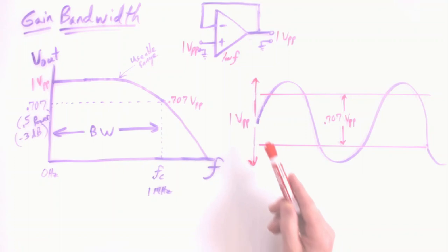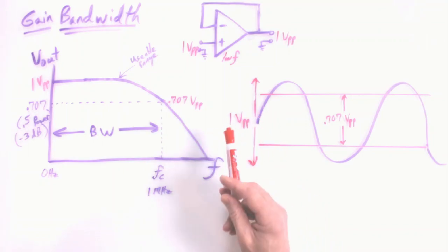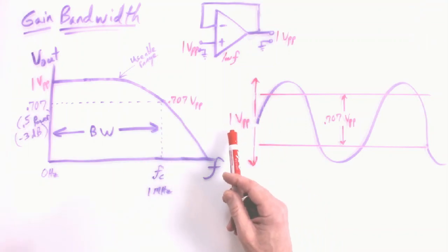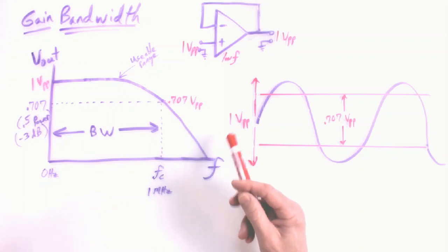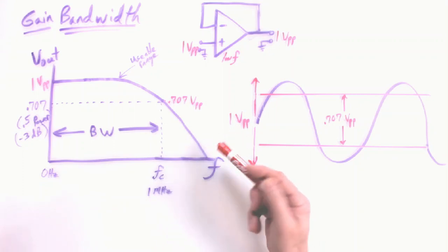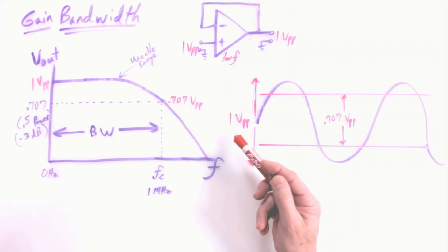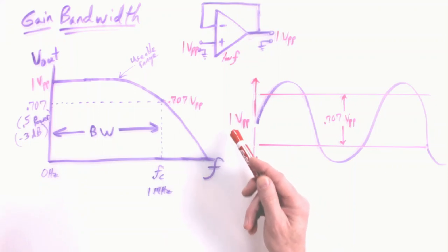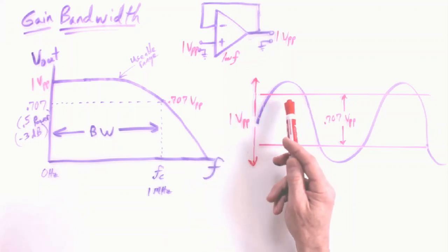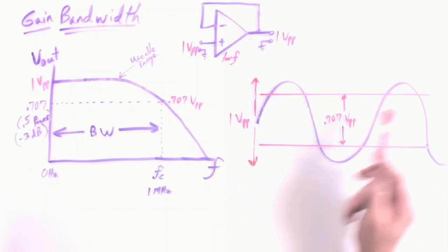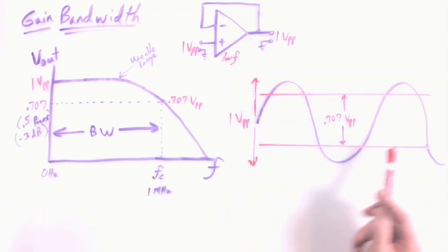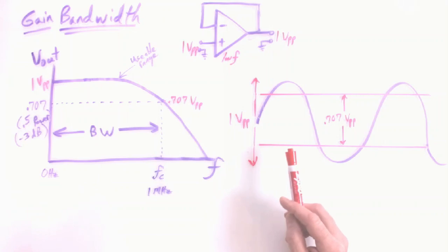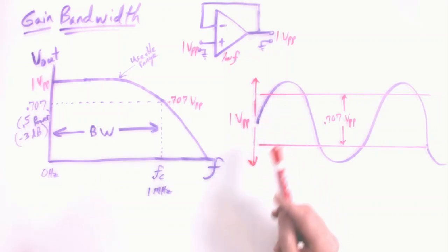But this is the time where you want to take your time to look at whatever this voltage is. If this was some odd voltage, like, I don't know, 2.36 volts peak to peak, take 0.707 of that, set up your cursors to mark the 0.707 value of whatever your peak to peak was. This then frames in the peak to peak amplitude that you're looking for.